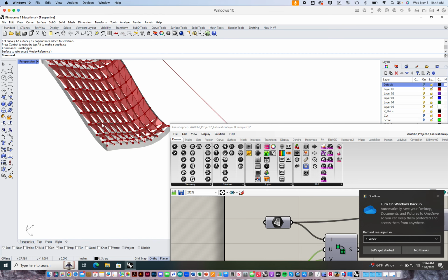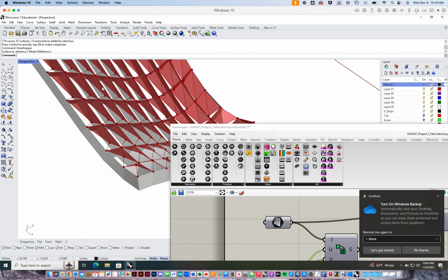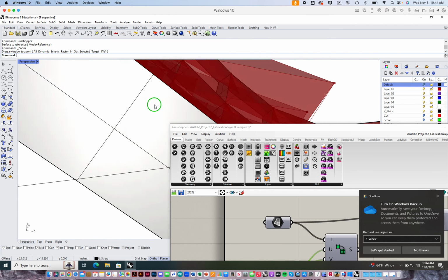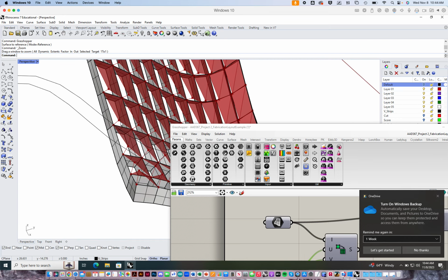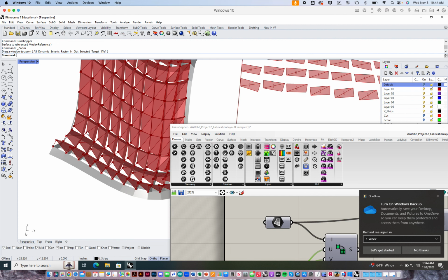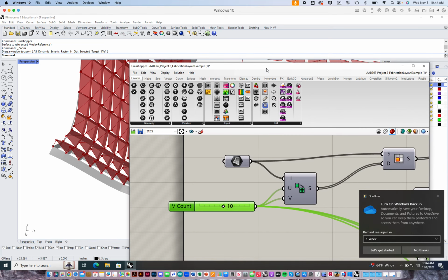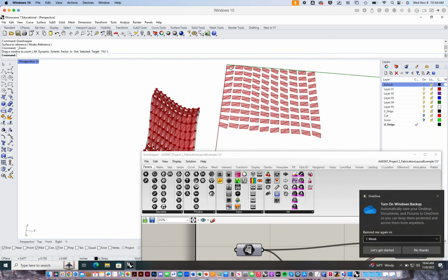Now these things should actually line up with, I'll turn this off and look, should actually line up with those ribs here. And in fact, they do. Look at that. Pure alignment awesomeness. All right, so there we are. This is like half a pyramid projecting out over the cell. Again, this is just the example I told you you couldn't do. And of course, we know for laser cutting, here's what we want. We want the outside edges and then any interior fold edges that we want to inscribe, score versus cuts and things like that.